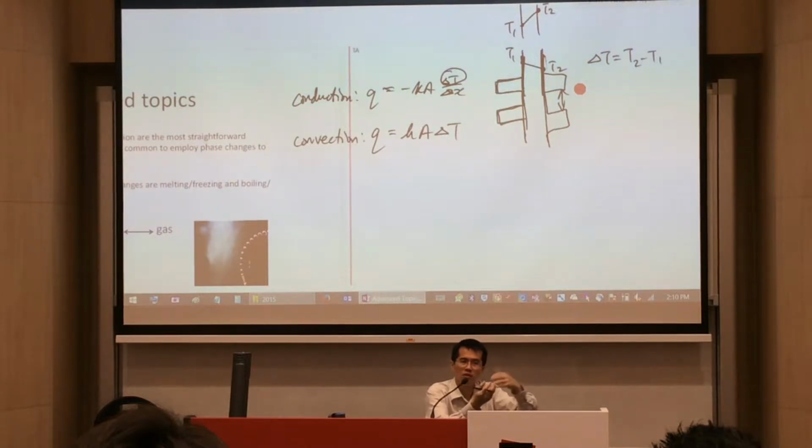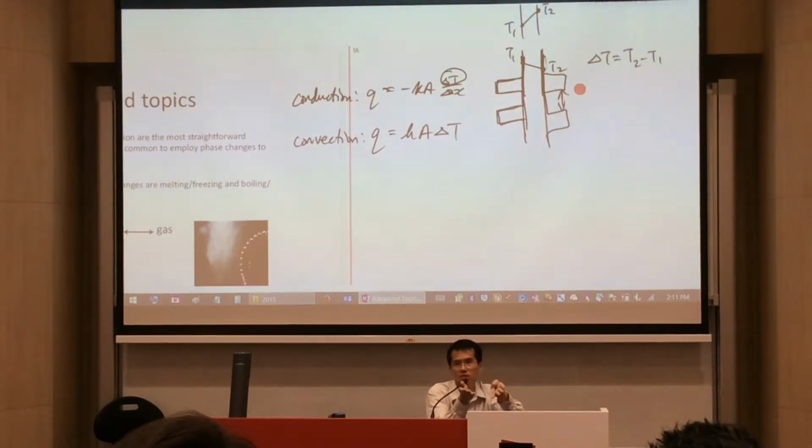You need to put in energy so as to remove heat. But if you don't need to put in energy, and let it naturally convect, then there is this interfin distance that will come into play. Not be too close. If it's so close as to interfere with the laminar boundary layer, then it wouldn't work. Okay. So another thing is also this thickness of the fin.